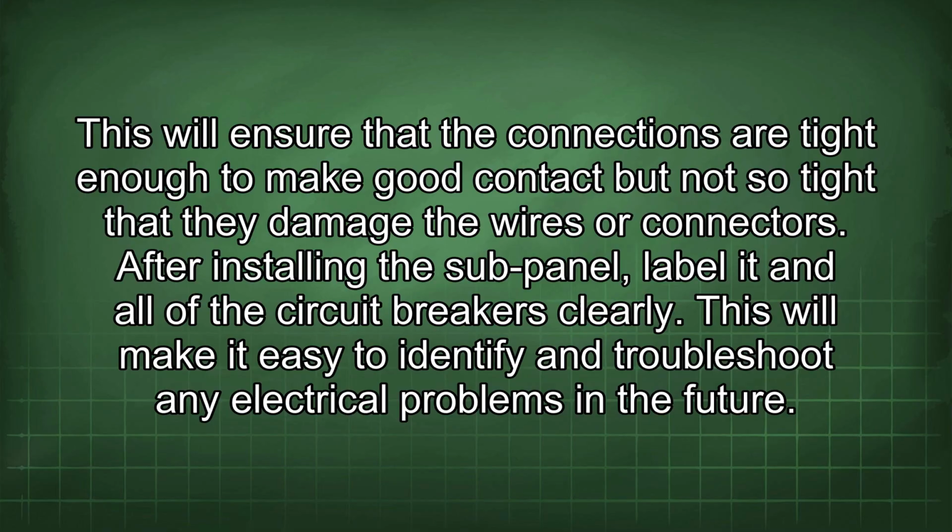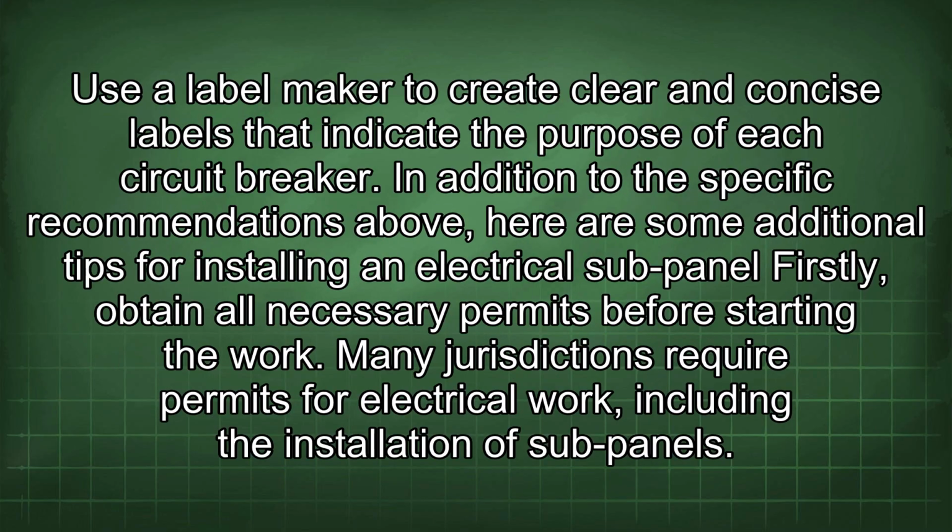After installing the subpanel, label it and all of the circuit breakers clearly. This will make it easy to identify and troubleshoot any electrical problems in the future. Use a label maker to create clear and concise labels that indicate the purpose of each circuit breaker.